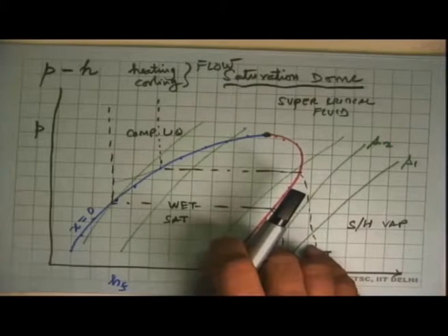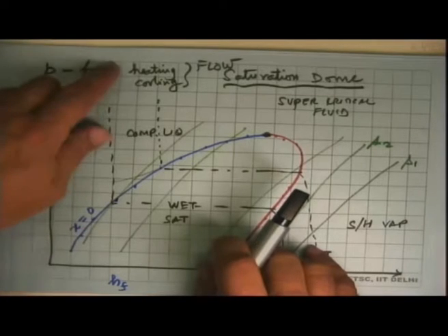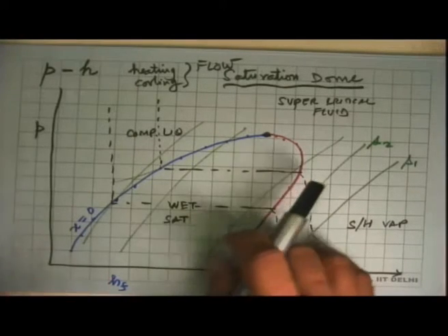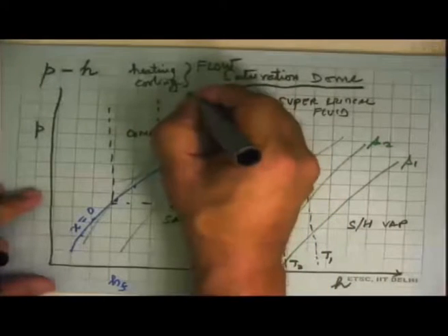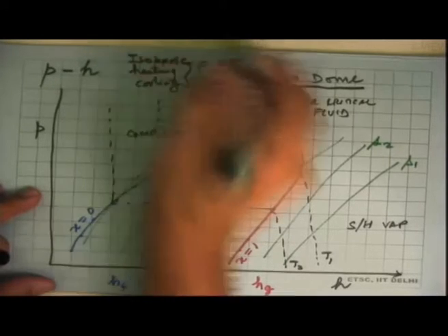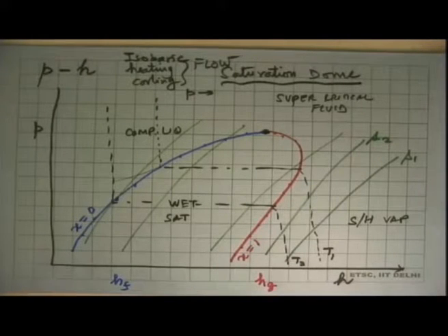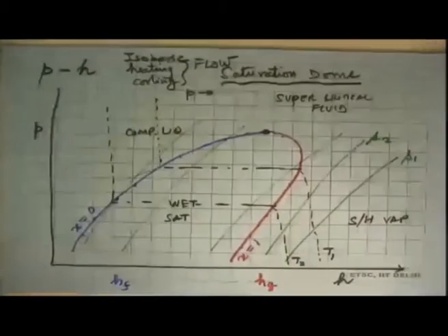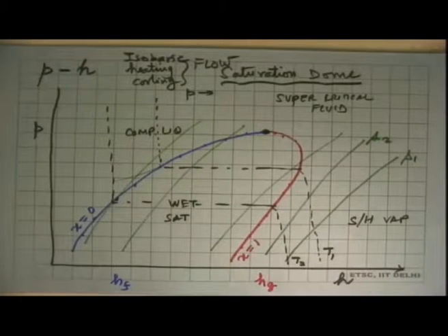In the first cut analysis in thermodynamics, we assume that flow processes involving heating and cooling and no work transfer are constant pressure processes, or isobaric. That's an important assumption we'll make in this course: wherever we look at a flow system and we look at either condensation or heating or cooling, we say that it is isobaric, which is an approximation to the extent that we are neglecting pressure drop in the pipe. Pressure drop is what one would have learned in a fluid mechanics course. It's a good first assumption.